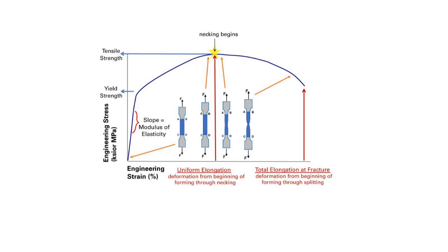So the extensometer must be removed before reaching the yield point. With the increasing load, at some point the load pointer remains stationary, which indicates the yield point. With further increasing of the load, the pointer goes backward and the specimen breaks. The maximum load before breaking is the ultimate load. The load at breaking of the specimen is called the breaking load. Necking is the large reduction in the cross-section area of the rod. Measure the diameter of the specimen at the neck.